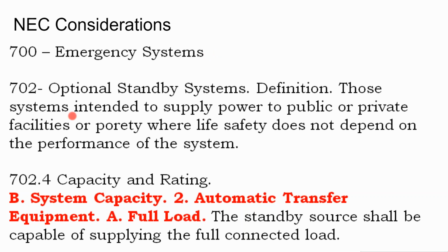Well, not even emergency, just for optional standby systems. Life-saving equipment could have additional requirements. Says the automatic transfer equipment shall be capable of supplying the full connected load.